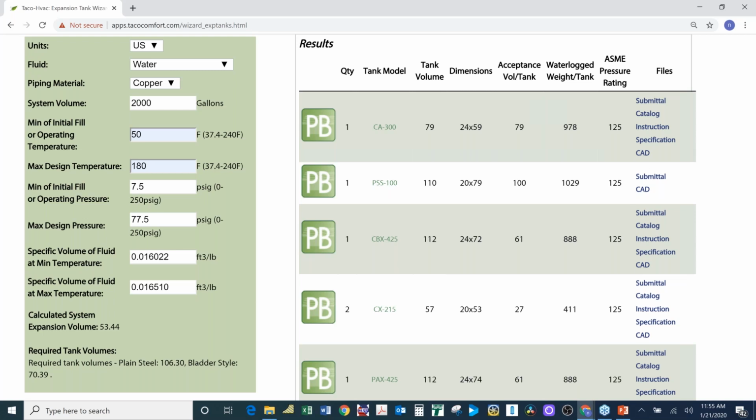If it has no place to go, it'll break the equipment in the system. So yes, chilled water systems should always have expansion tanks, and they should be sized for a maximum temperature of around 100 degrees to be safe. And you can use more than one expansion tank, correct?